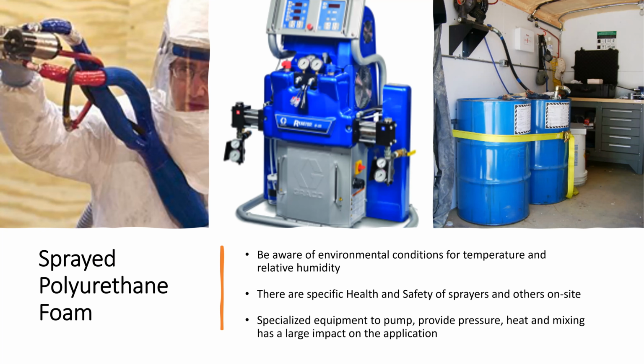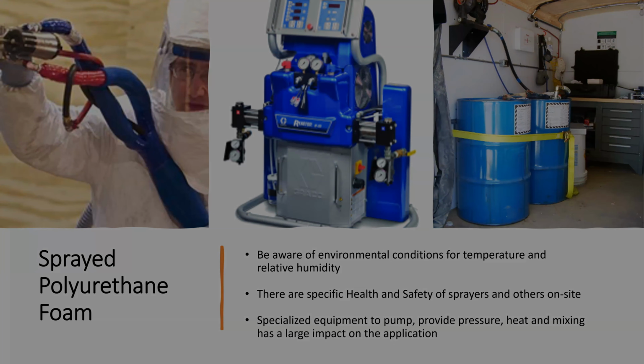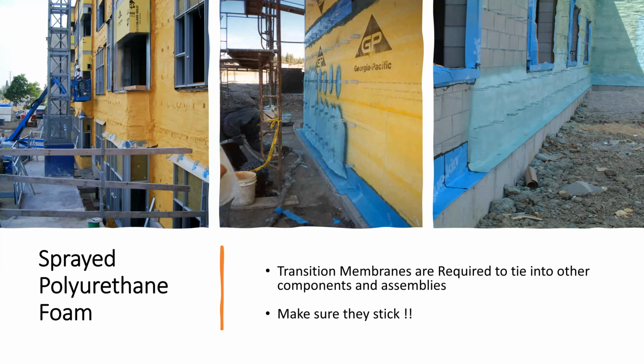It is very dependent on the qualifications of installers, because in essence, they manufacture. They're buying two chemicals and actually making the reaction. So they are the site manufacturer, and things can definitely go quite wrong, quite sideways, quickly. One of the things with spray foam is that it needs to be used in conjunction with transition materials.